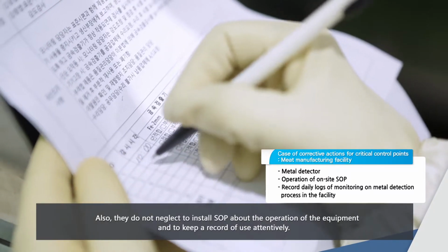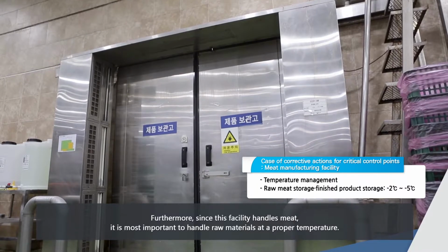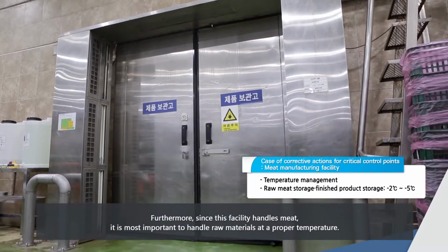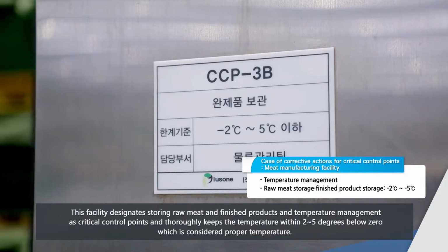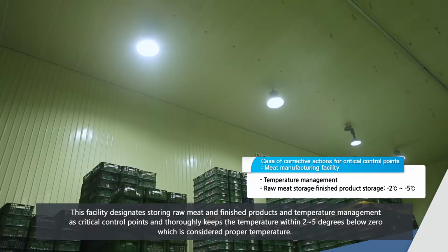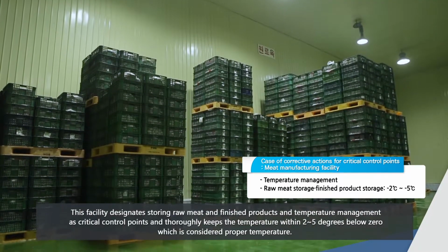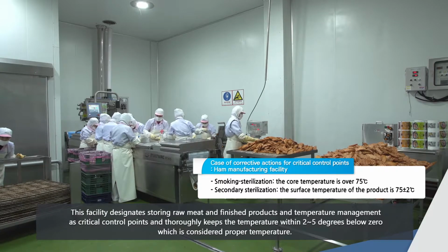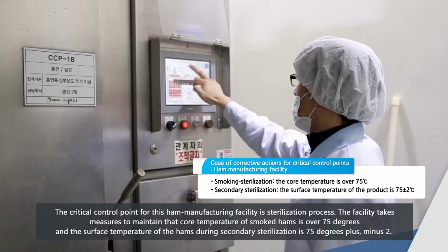Furthermore, since this facility handles meat, it is most important to handle raw materials at a proper temperature. This facility designates storing raw meat and finished products and temperature management as critical control points, and thoroughly keeps the temperature within 2 to 5 degrees below zero, which is considered proper temperature.